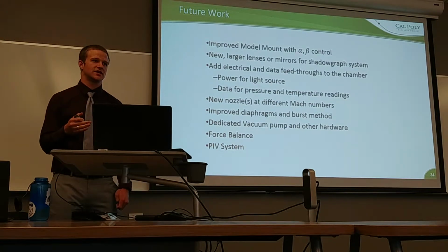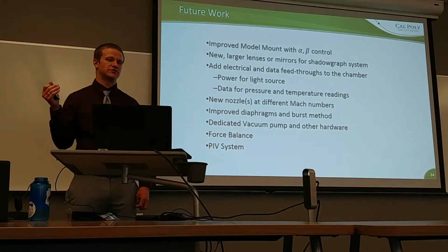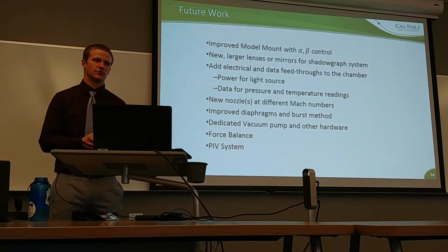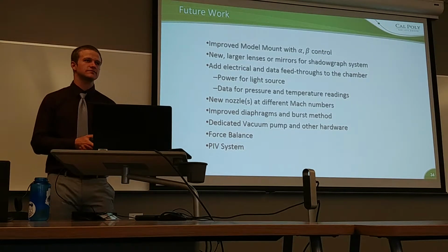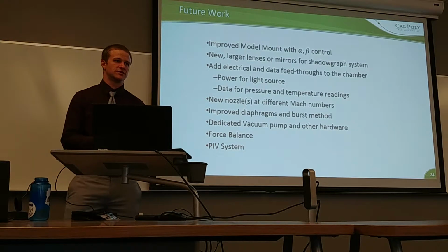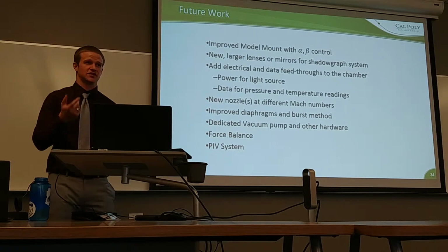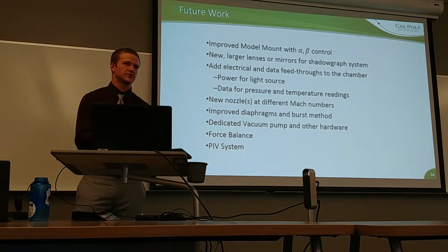So before we got to the test pressure we needed, it would slip out, rupture, and then flow through, and we'd have to reset and repump. The design diaphragm thickness was to have 0.04 of an inch of cellophane or 0.01 of an inch of mylar.